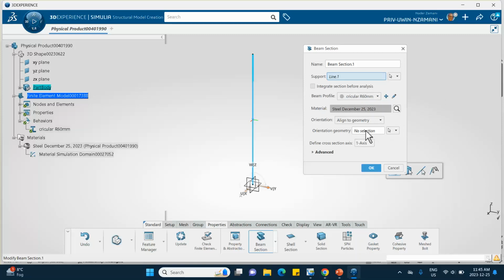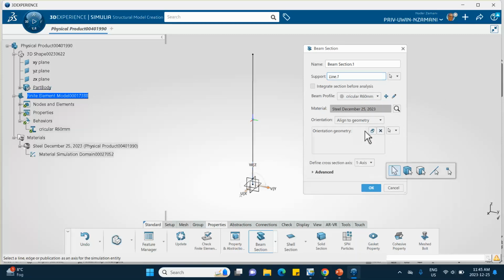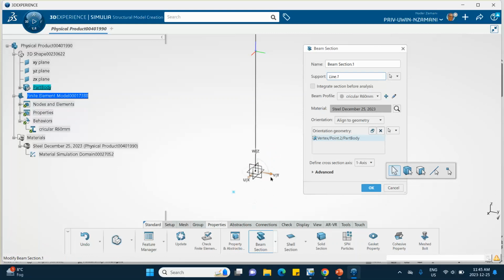And then notice that the geometry orientation, this is something that's needed. That point, I have to select it. Let me zoom out here. This point needs to be selected, otherwise I won't be able to close that, okay? So let me show you. Cancel this for a second, okay? So if I remove this, okay, then in some of the software you won't even be able to close it, but this is if it's not circular. But here, because it's circular, you don't need this orientation point.